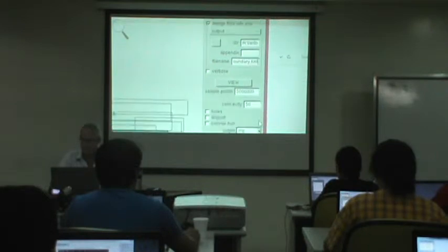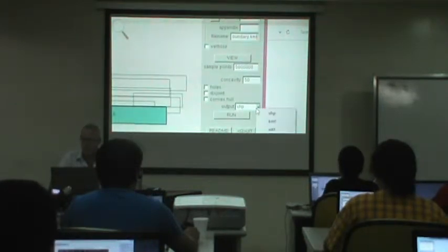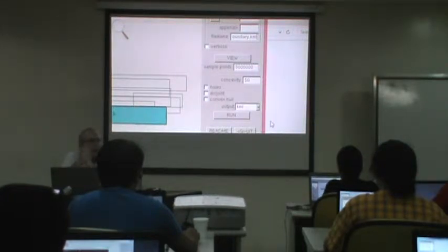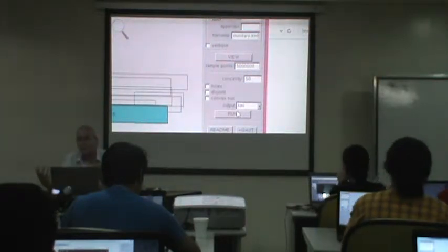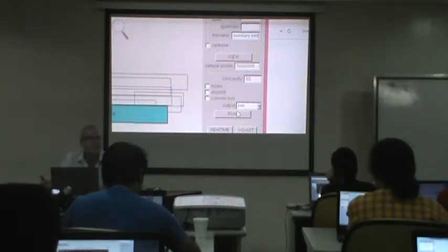Boundary.kml. So I'm choosing a KML format as the output. The nice thing about the KML format is you can display it in Google Earth, so you can just send it to your friend and say, look, the cool LiDAR I collected, or I'm working on, it's right there. The LiDAR itself isn't being sent, and LiDAR is very expensive, but you can communicate easily to somebody where you have LiDAR.